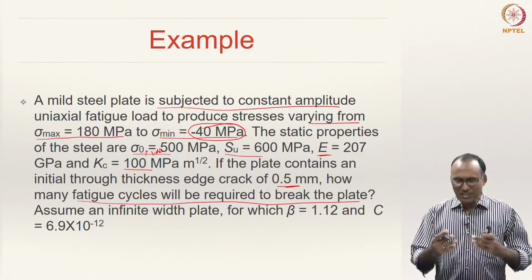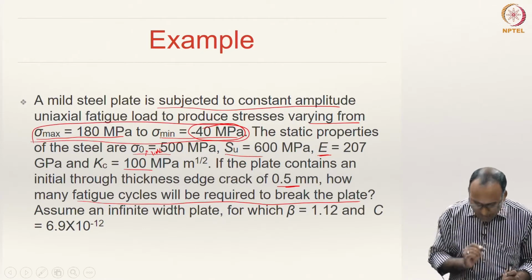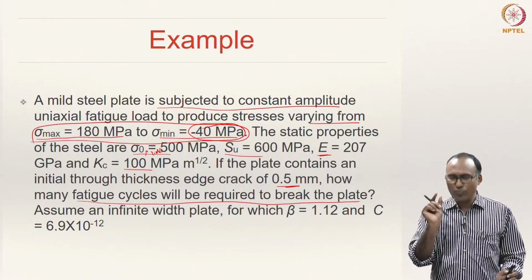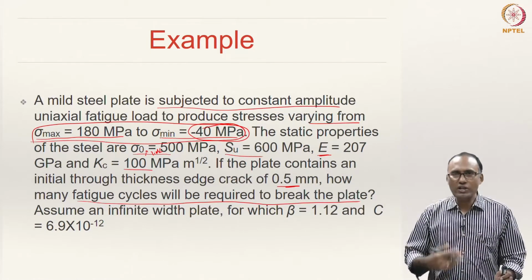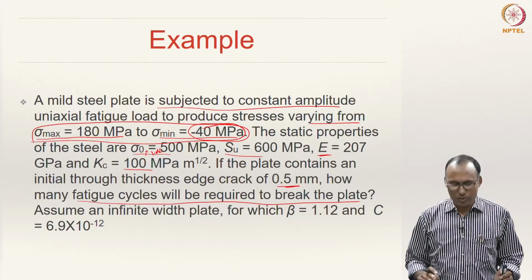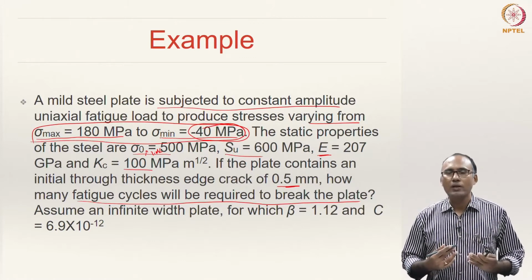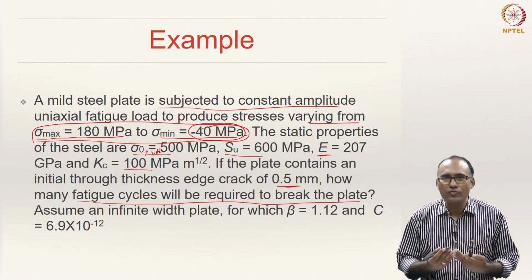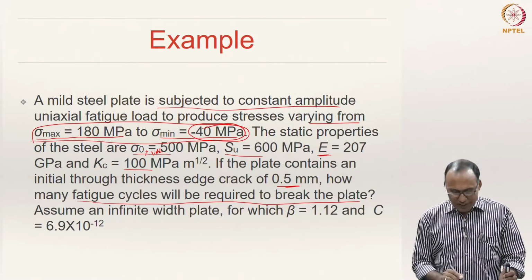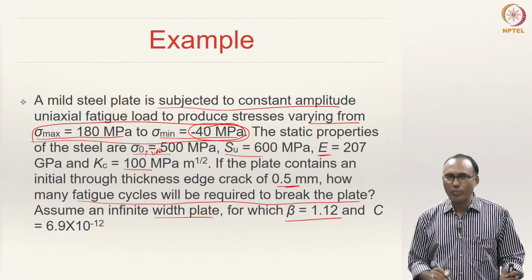How many fatigue cycles will be required to break the plate? So, you know the material and you know the loading scenario, and if you have an initial edge crack length of 0.5 mm, the question now is how many fatigue cycles will be required to break the plate. That means, how many fatigue cycles can this component be used for before it actually breaks. You assume an infinite width of the plate, for which beta equal to 1.12.